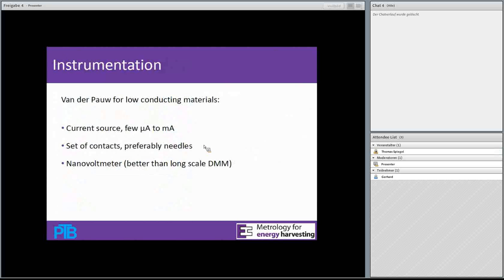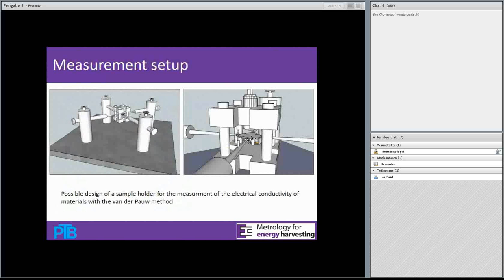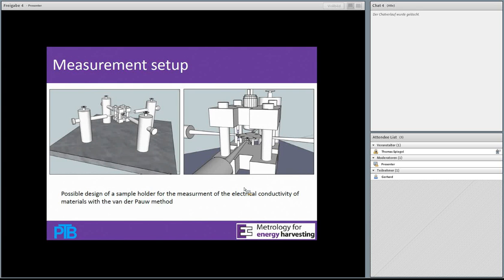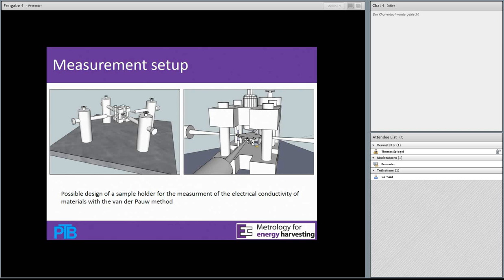It's difficult. With things like the Greek cross method, we did try some in this way to overcome some of the disadvantages of this point contact method. If you look carefully at this picture, you can see this was one sample where we put in some slits to get a sort of cloverleaf structure, which is similar to the Greek cross effect, but easier to manufacture. With such a method, you reduce the effective area that you investigate, but you get rid a little bit of these point contact problems.